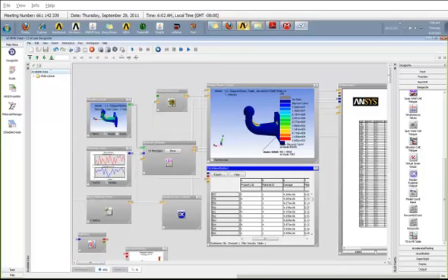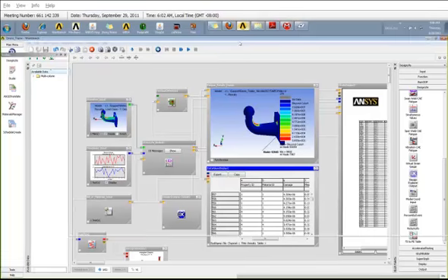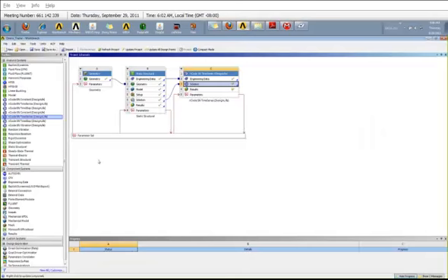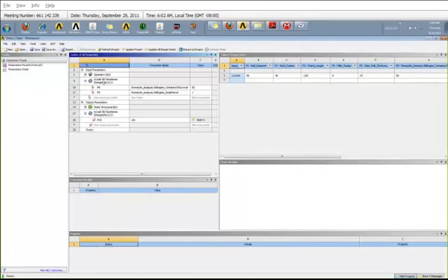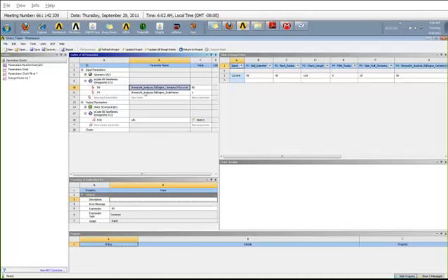Okay. So now let's go back to my Workbench project page, and let's take a look at all these parameters. So it basically created a parameter set coming from my CAD static structural. In addition to that one, it also created a parameter set coming from my nCode DesignLife. Now let's go ahead and open up this parameter set over here. So it has some input parameters that are coming from the geometry, which I will talk about in another couple of minutes. So these are the input parameters that are coming from my SN time series, so certainty of survival and the scale factor,